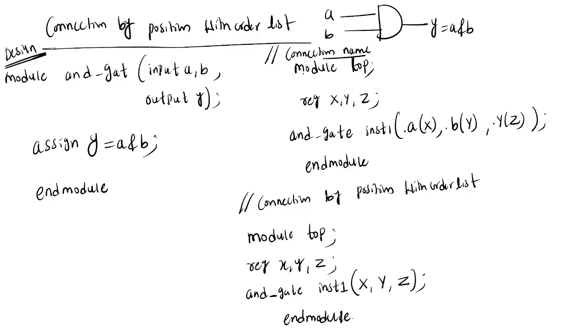Similarly, parallel adders. We design parallel adders, that means ripple carry adder, BCD adder or carry look-ahead adder. We implement those parallel adders by using full adder circuits. There we use four full adder circuits, so every time we can't write the code for each full adder; the programming length would become complex.